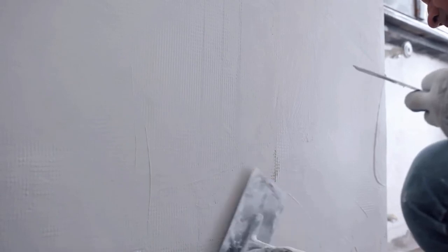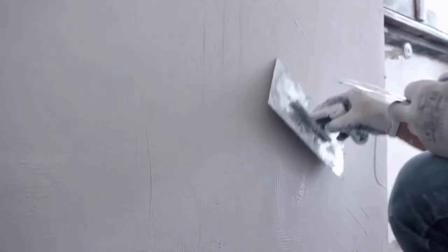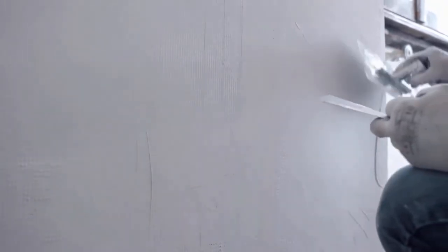Then we need to apply the second coat. Apply in the same direction as the first coat for uniformity, and let it dry completely within 6 to 8 hours or as per the manufacturer recommendation. And then final sanding, and it is ready for the painting work. So before that you need to do the final sanding, and you need to check whether this is in line or level or not. So what is the checkpoint?